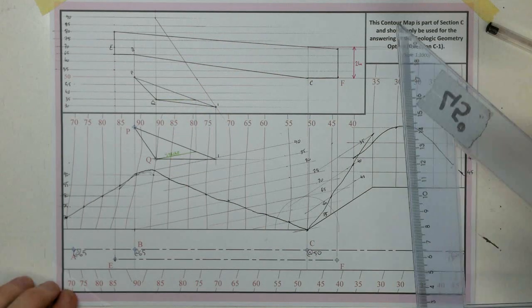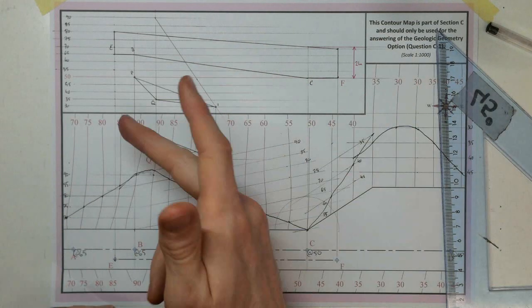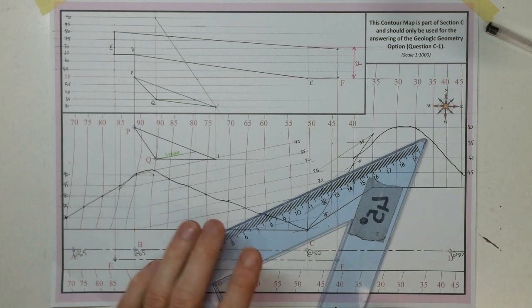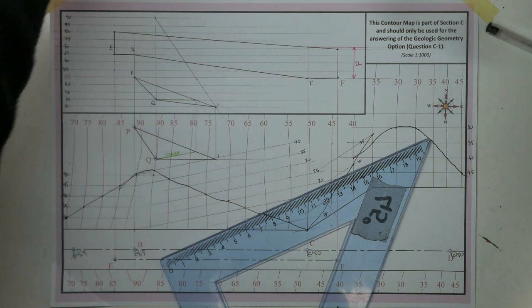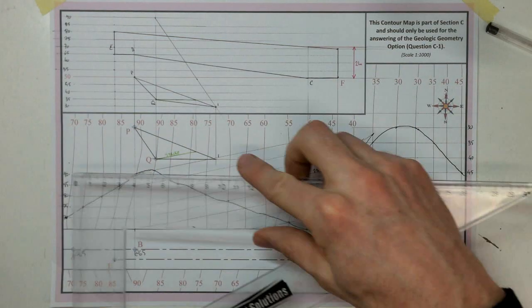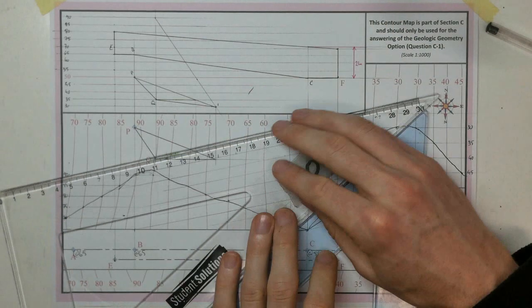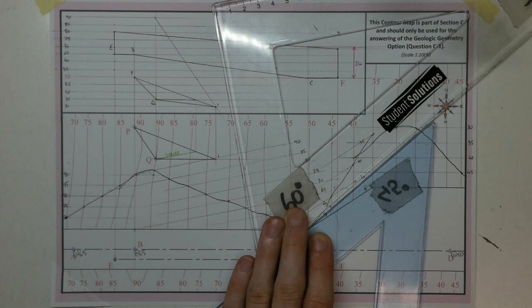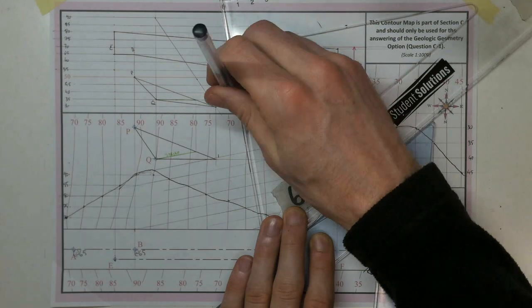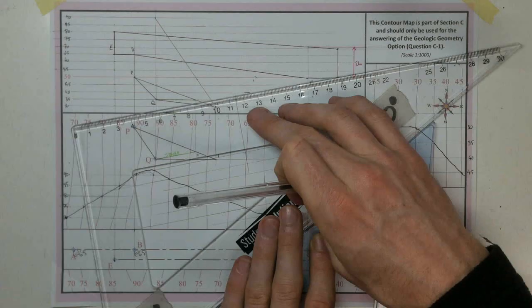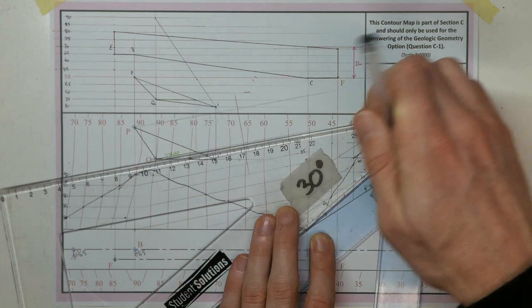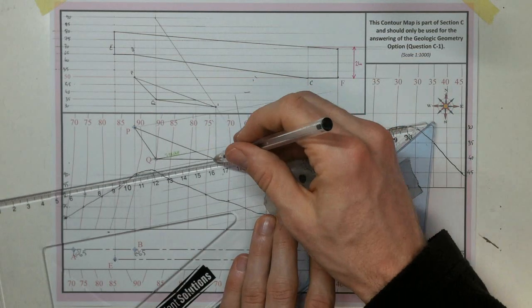We want to find the dip, so in order to see the dip we need to see this surface as an edge view. We're going to look along our strike because our strike is a true length line. XY line, project out P, Q and the strike, and A1.